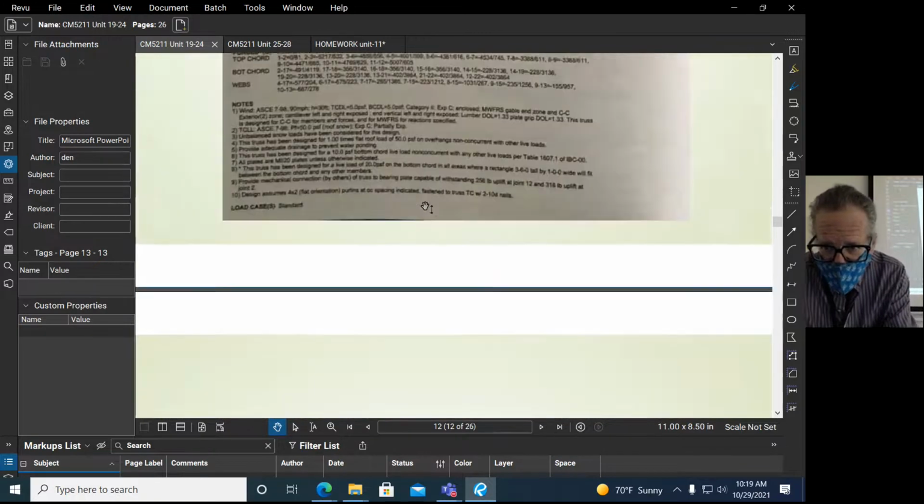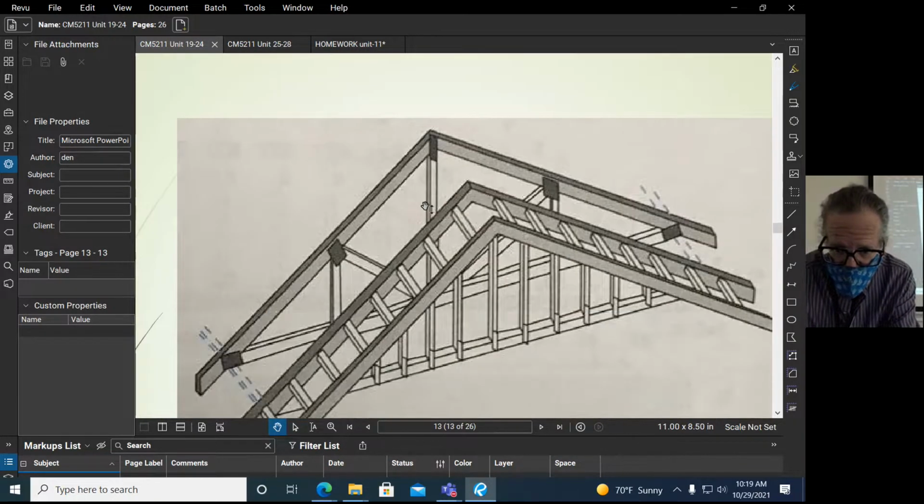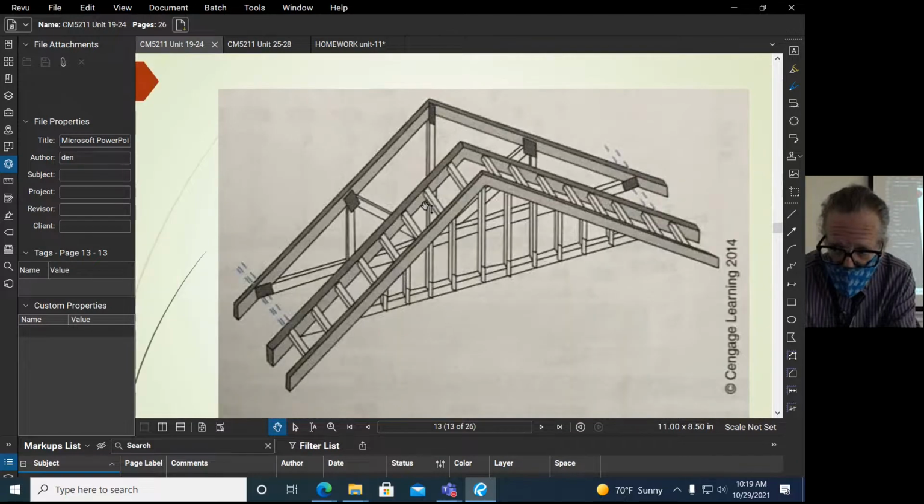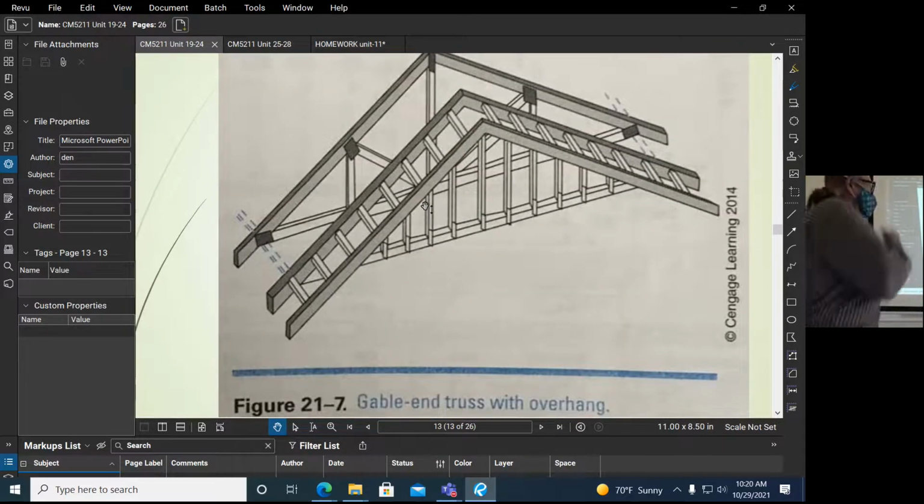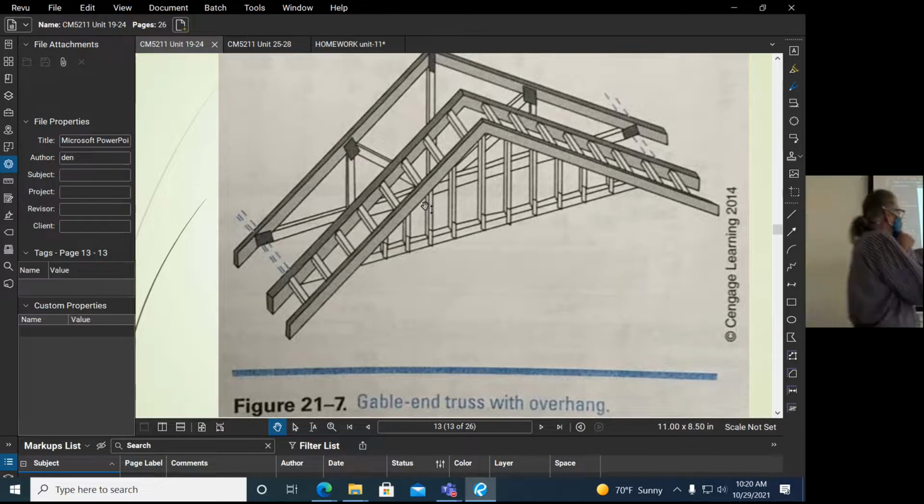Just more detail about these trusses. And then this is kind of how you would frame out the gable, the end condition. So this is the gable end truss. It has the additional vertical stud members in it. And then you frame out this ladder out to the outside. And then usually you'll attach some plywood to the bottom of that and have ventilation in there to make sure that everything's properly ventilated. And inside the building, where it's not a gable end truss, this is where you can have this open web truss.